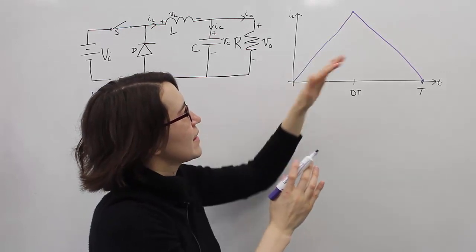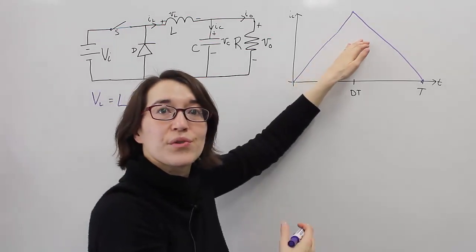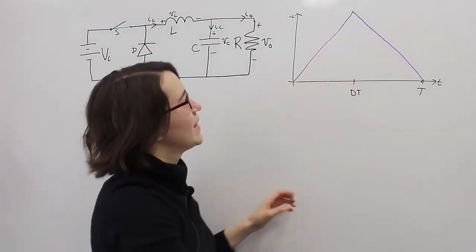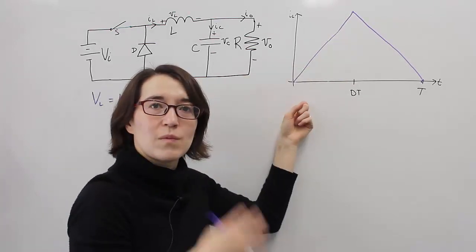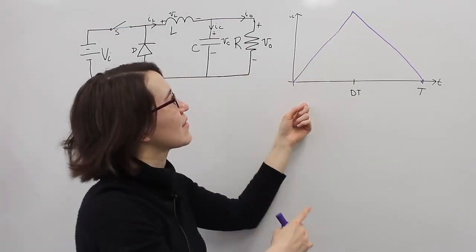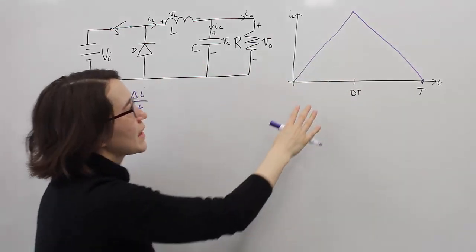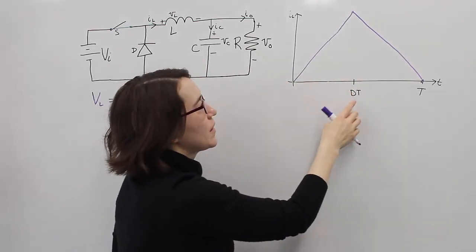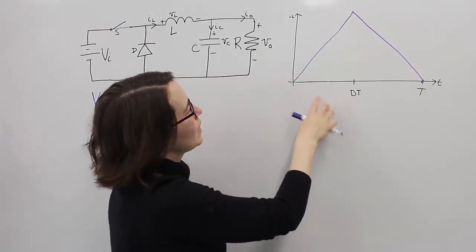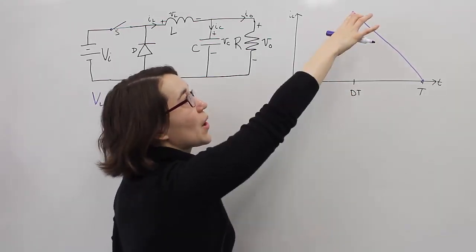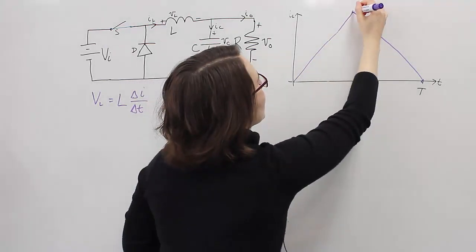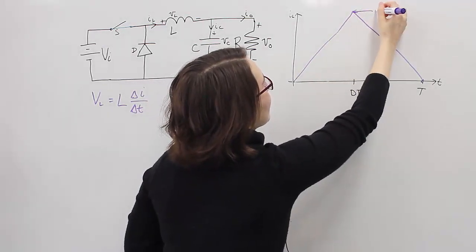If we calculate the inductance at this value, this is called the critical inductance value. So first, we assume let's operate in BCM, and let's find this inductor value that exactly fits this. So we're going to start with looking at just this period. So when the active switch is on, we'll calculate just the going up part. And what we need to know is we need to know this value. This is I peak.